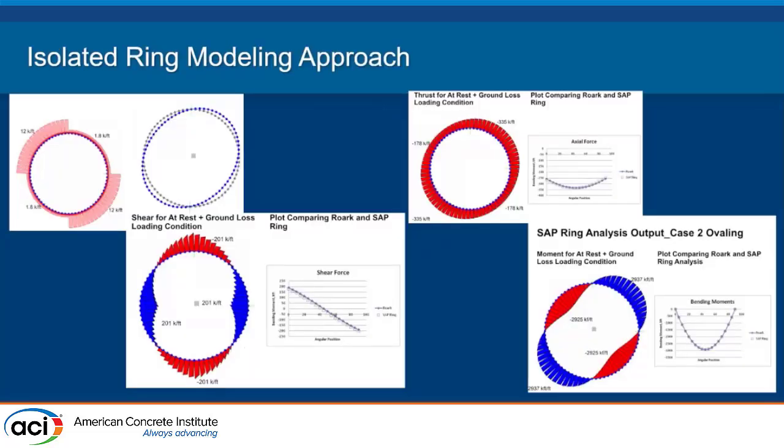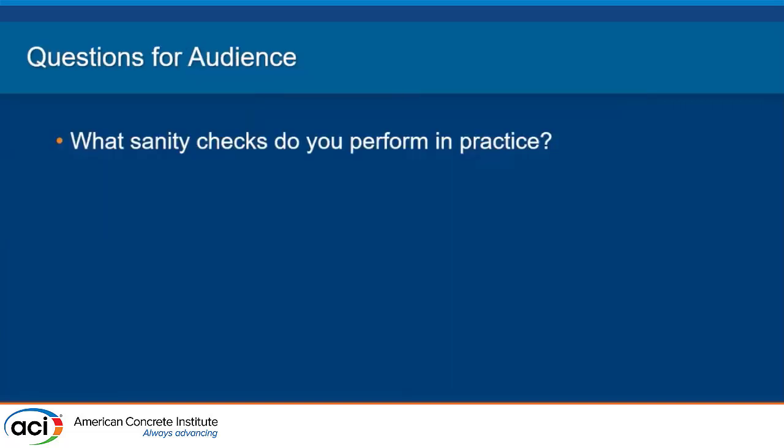We didn't just do that finite element model. We also did simple ring calculations. We did Roark's formulas, so I had to do it by hand first. And so we checked a lot of this work the whole time. I think it's just a good example of building up complexity as you go.